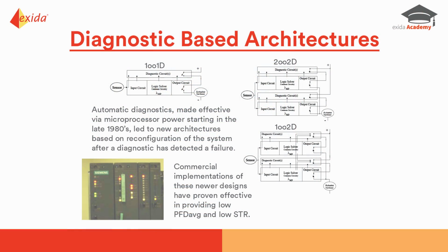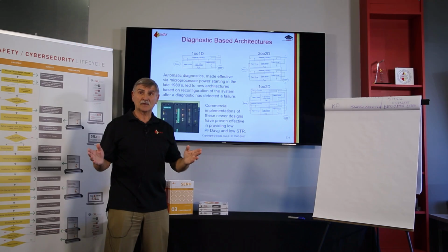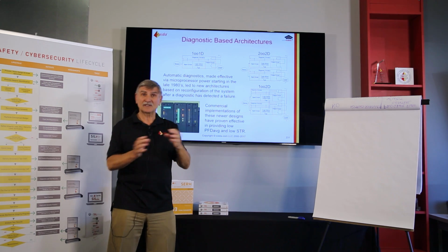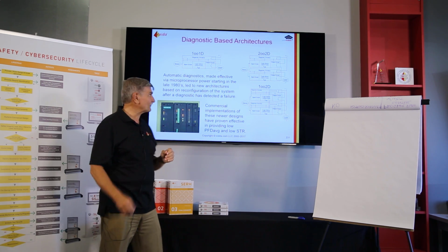Look at this. A diagnostic switch is wired in series with the main switch. If you've got it programmed to automatically trip on a detected failure, the diagnostics will say, it doesn't work anymore. Open up the D switch, output de-energized, fail-safe. That's what I mean by converting dangerous failures into safe failures.